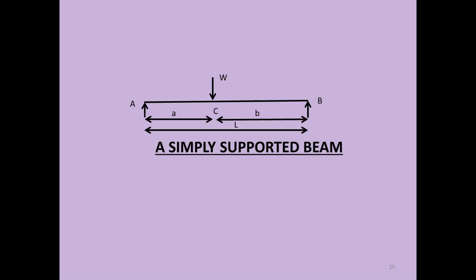It is going to be found at the two sections of the beam, and then these two moments are going to be substituted in the governing equations to have a number of unknowns when the differential equation is going to be integrated twice. The unknowns obviously are going to be found using the boundary conditions and some other conditions which are going to appear on its own.